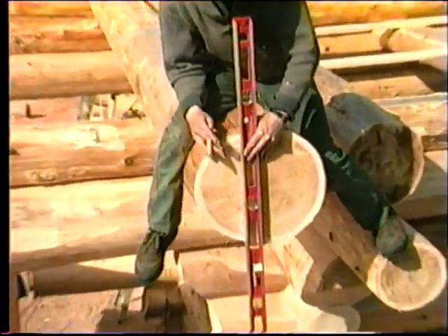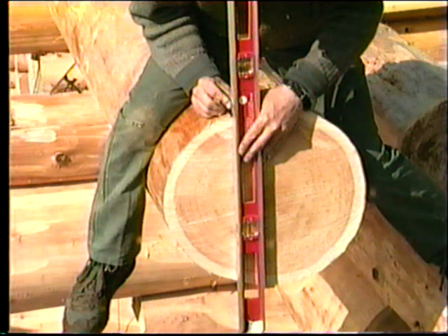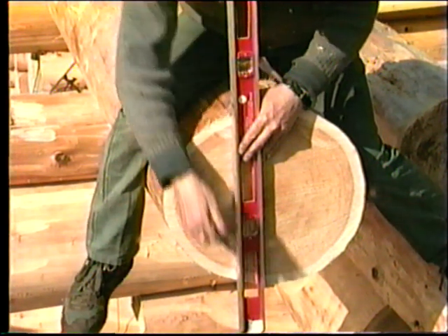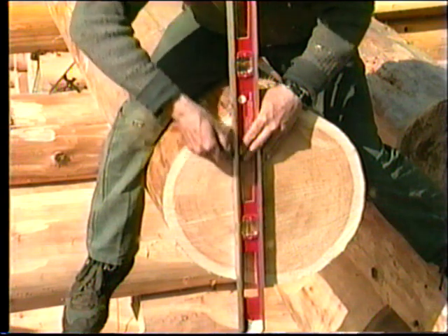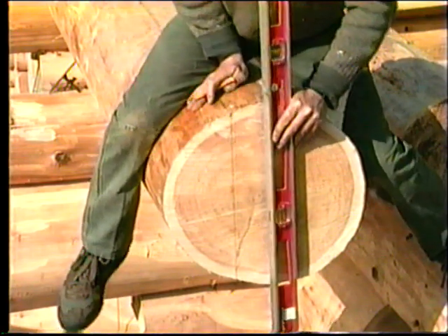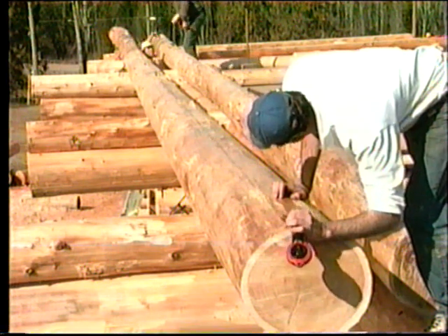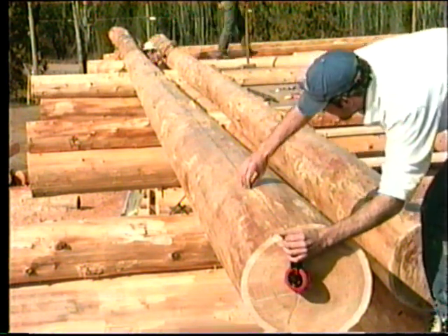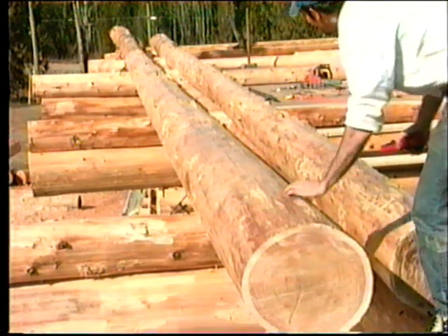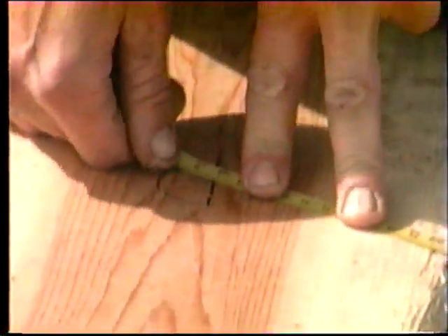Ideally, the plate log will be set out a very little at the top end, 15 millimeters, and a very little in from the center line at the large end. The length marks of the wall should match the center line on the gable end wall, and these intersection points should have diagonal measurements that are within 5 millimeters.